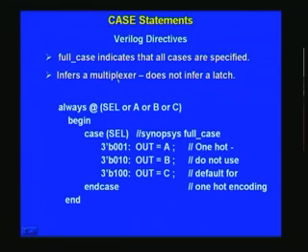For the time being we will see how this does. There is a directive called synopsys full case, full underscore case. This looks like a comment, but it is a directive, it is more than a comment, right. So, take care that you do not put this as any of your comments. If you do, you will get into trouble, right. What all it signifies for the synthesis tool or even a compiler is that we have given only a partial list here, we have not given the entire thing, but you regard it as a full case. That is what the implication here is. So, just by giving this here, you do not have to list all the conditions, right. Is it clear to you what a full case is?